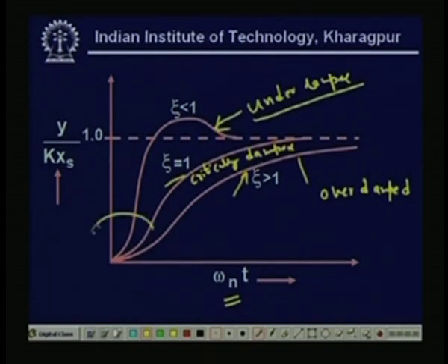Now, look at the origin of the systems. If you look at the origin, you see there is a distinct S curve in the system, and this will tell you that even if you do not know whether the system is first order or second order, by looking at the origin I can tell whether it is a first order system or second order system.